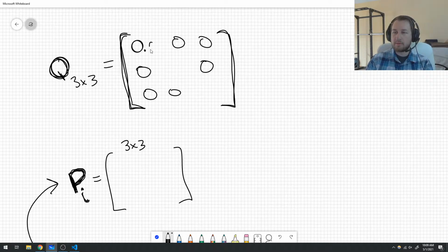So let's say it's 0.01, and let's say the velocity is even 0.001. The velocity will follow the acceleration, but the acceleration here, I don't think it's going to be constant, right? And so I would put this as a much higher number. And this is where tuning the Kalman filter comes into play, finding these numbers that you need, and just seeing what the Kalman filter gives out in your graphs and stuff.